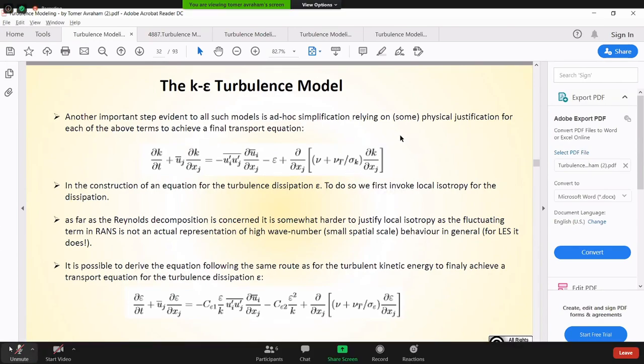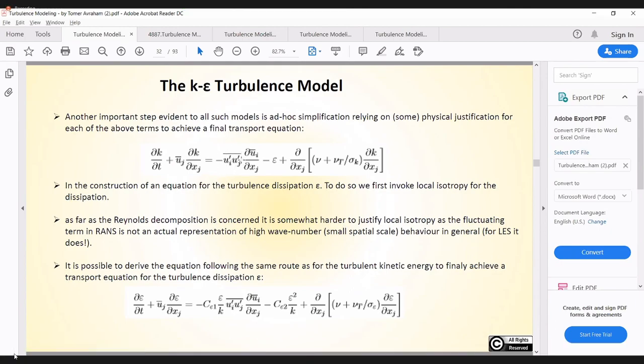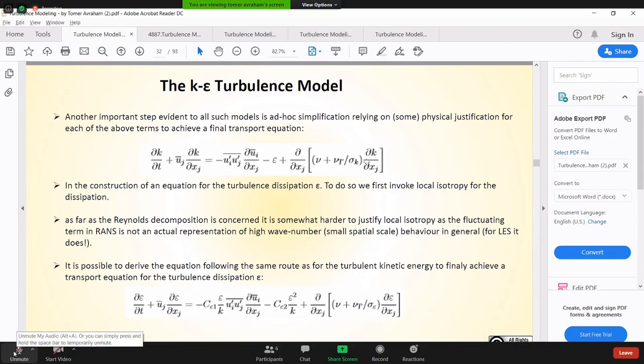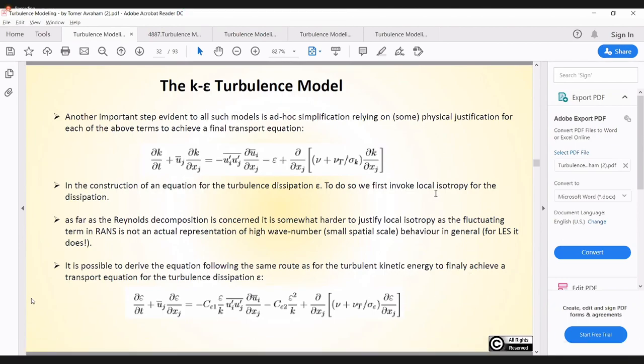We are left here with no perturbative velocity except the Reynolds stress, which we can switch for a constitutive law, because it's mu t times the gradient. This is the gradient assumption. This is the dissipation. Ad hoc assumptions means that they are not in any way justified.